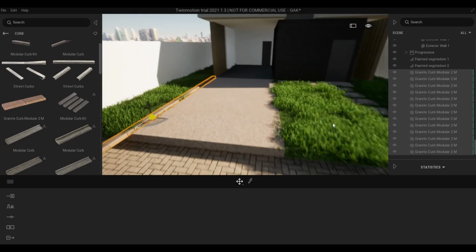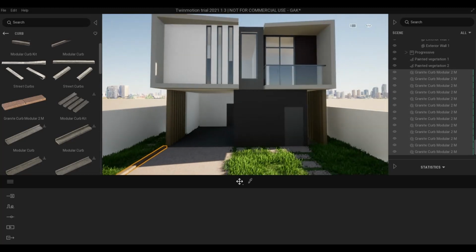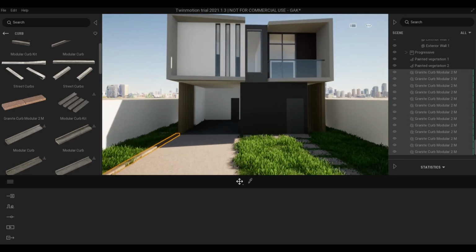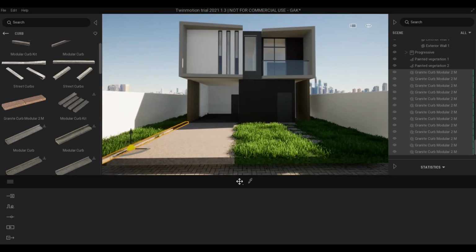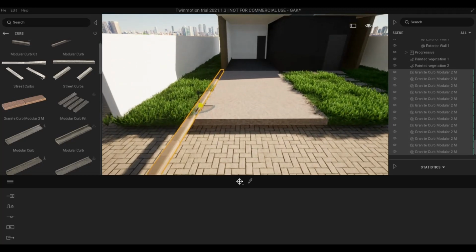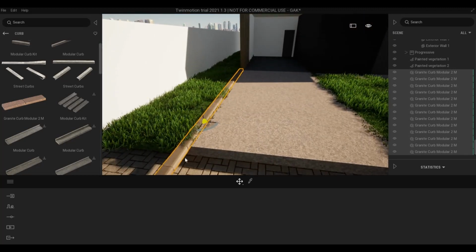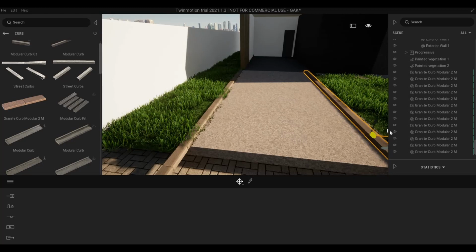And I'm planning to extend this more because of the height of the building or the house. So I want it around here. So we could go back to Revit so that I could show that to you. And then now, because all of this still selected, I'm gonna hold on shift and I'm gonna put it on the other side like that.